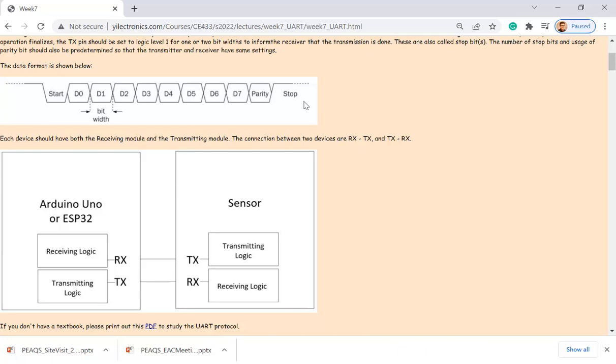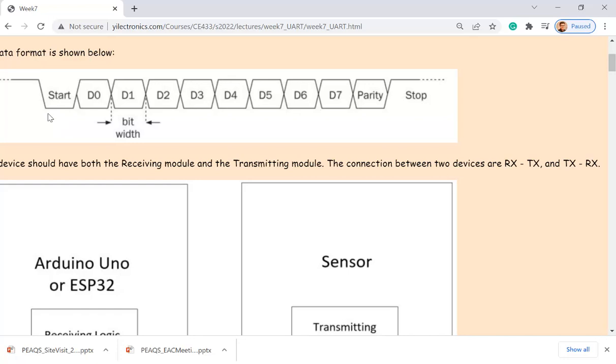So I have to pull it down first. So it's sensing a 0 first. I keep high here, so you are receiving the same wire. I pull it down first, so you know it's getting started. But that 0 bit, which is the start bit, is not a signal. There's no data in there. So you can see here, it's just a start. It's just 1 bit, 1 clock cycle. There's no information. Just a start bit. So I have to pull it down first, like I tell Max, here's the information.